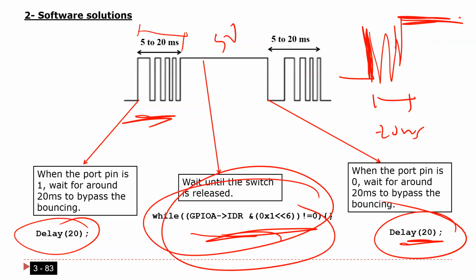I'm going to wait until you release. So I'm going to take action after you release. Even after you release, I'm going to wait 20 milliseconds. After that, I'm going to take the action. You got it, guys? In your program, you have to write this one, and then after that, you can take the action. Yeah, you press one button, you take the action.